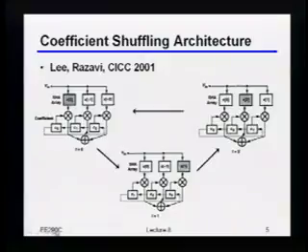And then we finally got to the receive FIR filter. So this is still linear, not DFE, just a linear FIR filter. And we basically said that on the receive side, doing these FIR filters, at least at the moment, is not particularly popular. The main reason for that was that, generally speaking, when you build these FIR filters on the receive side, that implies that you have to have these analog delays, right?